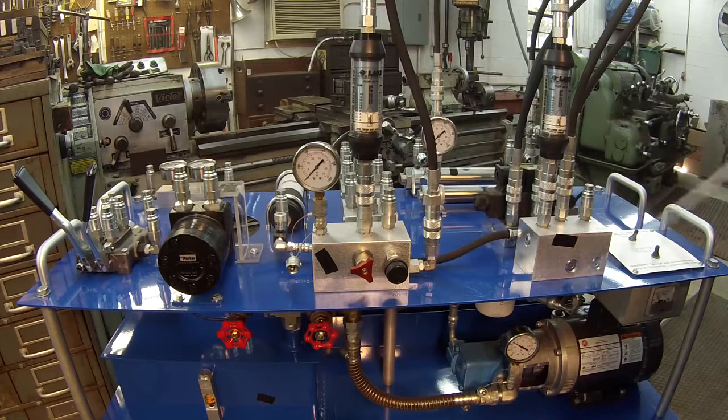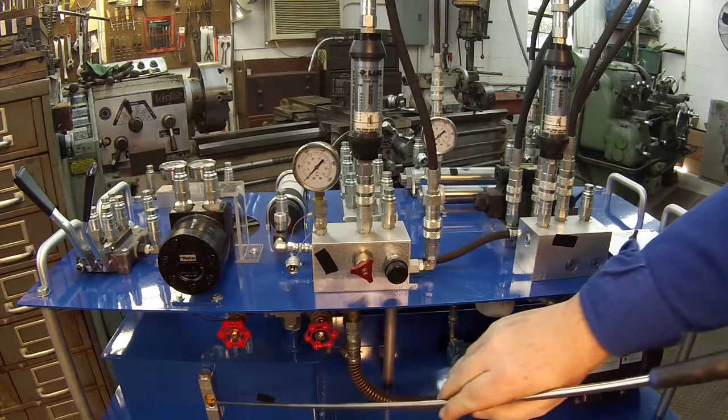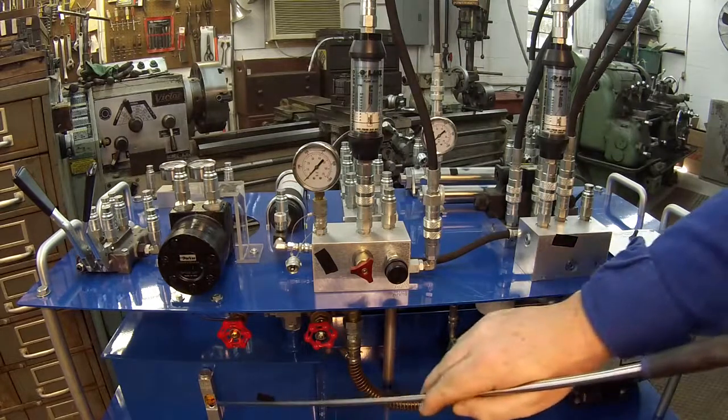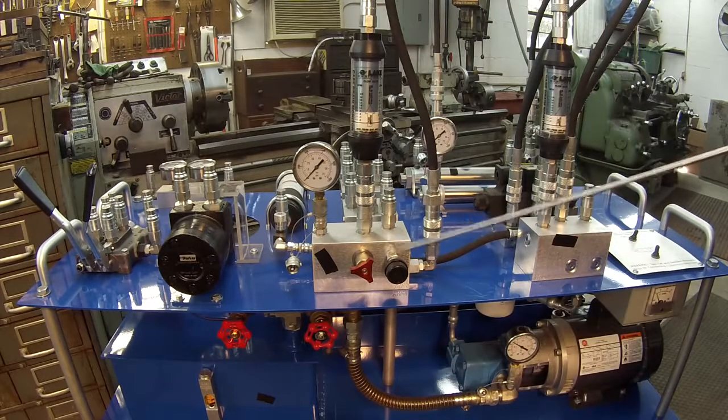So if you've got things sticking in your hydraulic system, that is because your oil is oxidized, and it'll start turning a dark color right there. You see this is a real light color, an amber color. When it starts turning dark, that means you've got heat in your system and that oil is oxidizing, and that actually tells your spools inside here to start sticking. Okay?